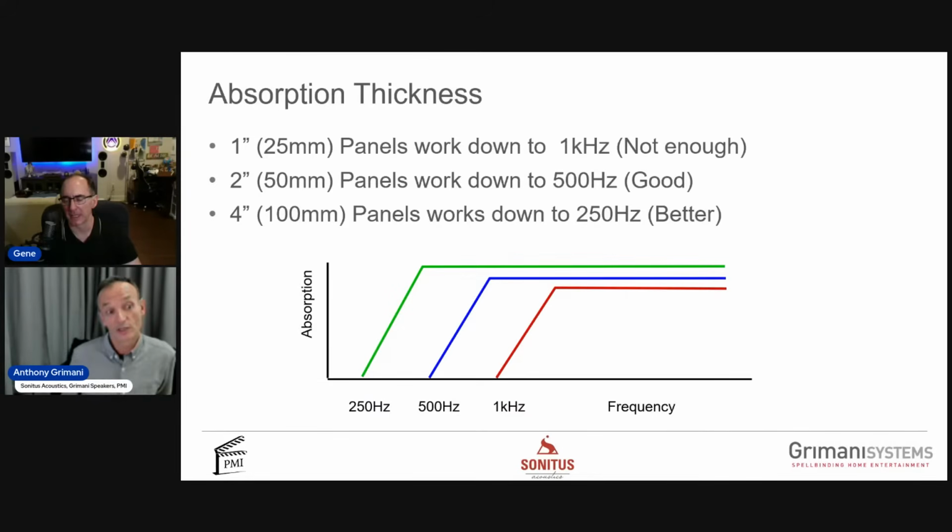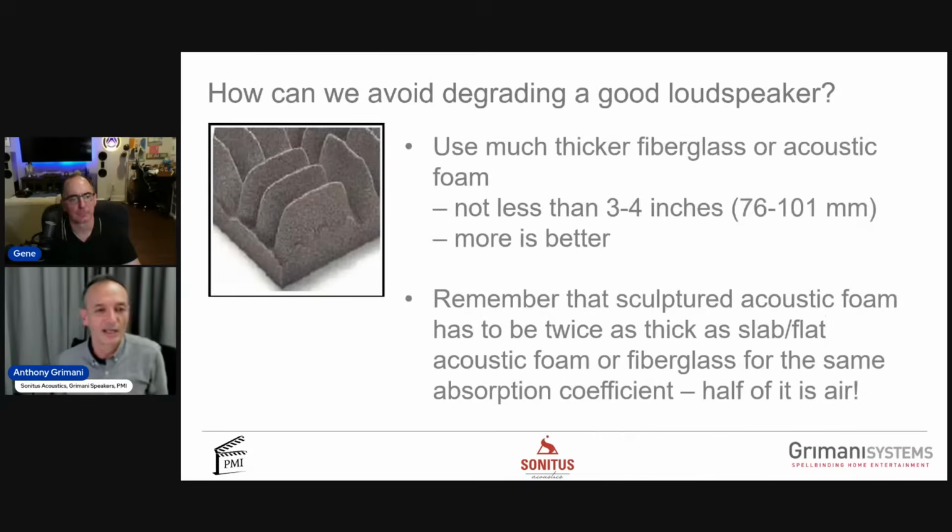And put a gap behind absorbers. If you put a 2-inch gap behind that, it lowers that effectiveness down another half octave, right? So a really good way to do a 1.5-inch gap is take a 2x4 or 2x2, put that on the wall behind the panels, and screw or mount the panels on that. You get a 1.5-inch gap. It's good for down to about 150 hertz. That's really good. That's the right way to do it.